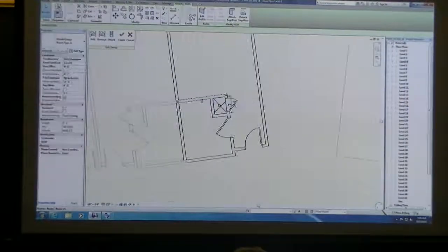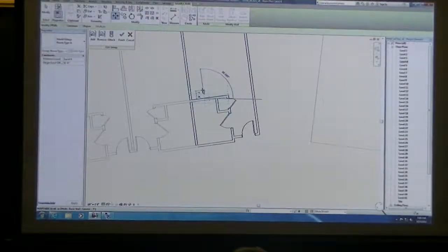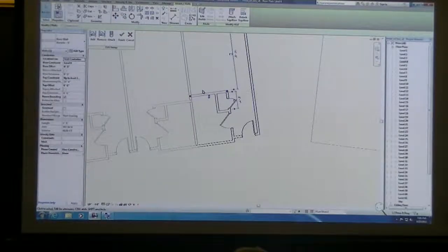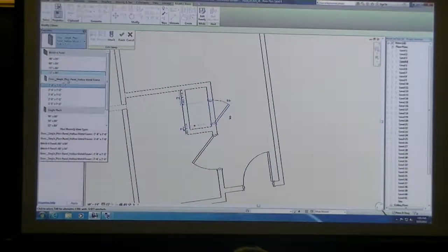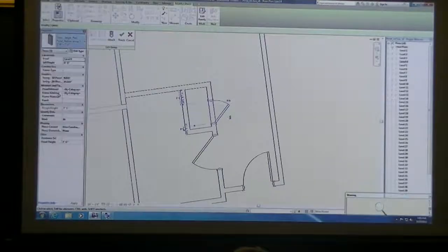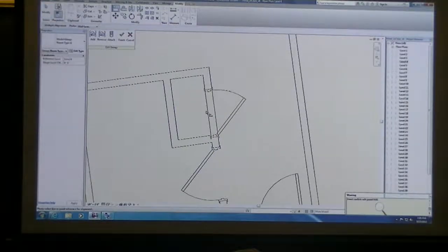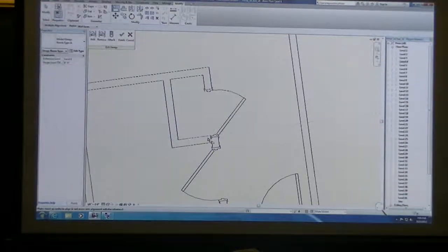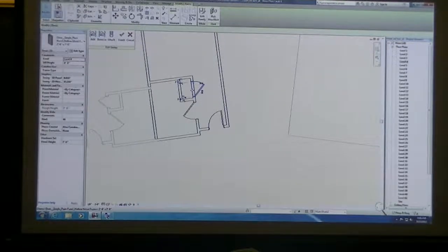And then I can come in here, and let's say I click on this wall and decide it actually needs to be moved, let's say 1 foot in that direction. I'm going to go ahead and make my edits, and maybe now I realize I can get a larger door in here. So maybe I'll make this a 2'8" door. And you'll get warnings every now and then when your door doesn't work out because it grew by the center line and then it's overlapping this wall. Now I can just go ahead and move this into place by using my align tool and getting it out of that situation. Or I could also just use the cursor keys and move it a little bit.